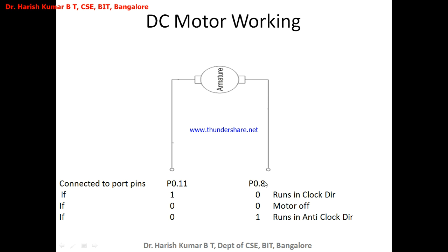In the last class I also explained that the LPC2148 has two ports, port 0 and port 1. In port 0, you can use the pins from P0.0 to P0.31. Totally 32 port pins are available in port 0, and similarly in port 1 you have 32 port pins available, but usable are only from P1.16 to P1.31. The pins below P1.16 cannot be used by the user.